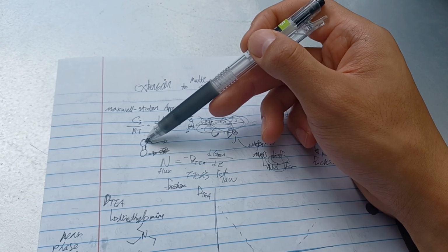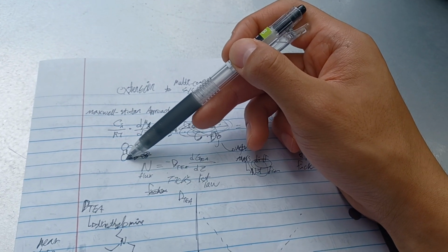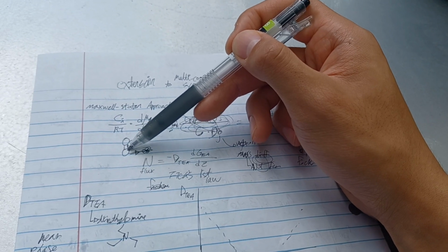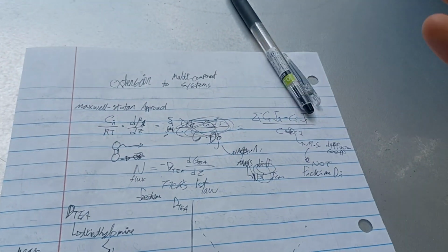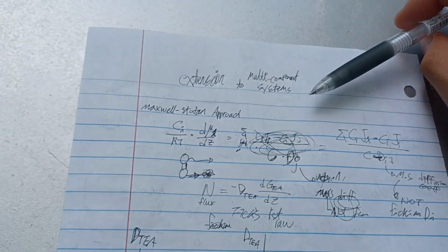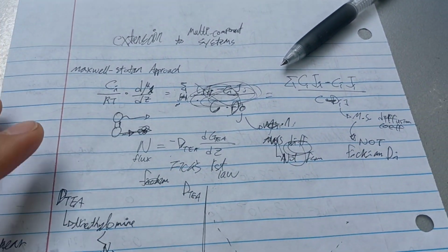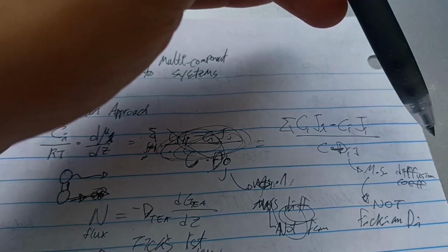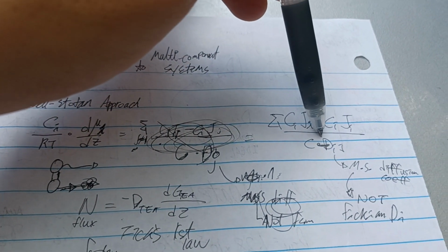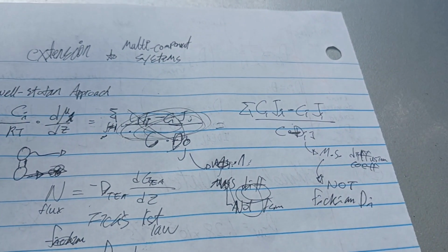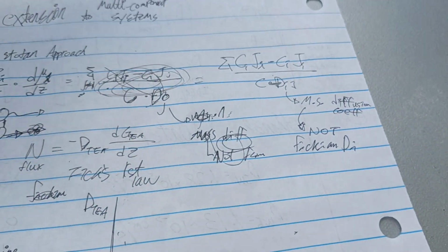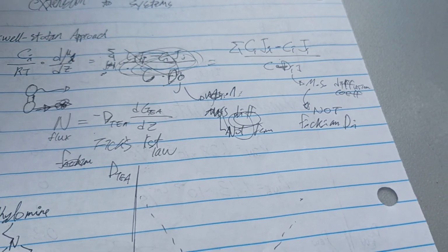They have this molecular interaction that's kind of pulling each other. So even this molecule A is kind of tagging on molecule B too. That's what the Maxwell-Stefan approach is really trying to explain, represented with this equation. And there we see this D dash again, the thermodynamically corrected diffusion coefficient. And we call this here the Maxwell-Stefan diffusion coefficient.